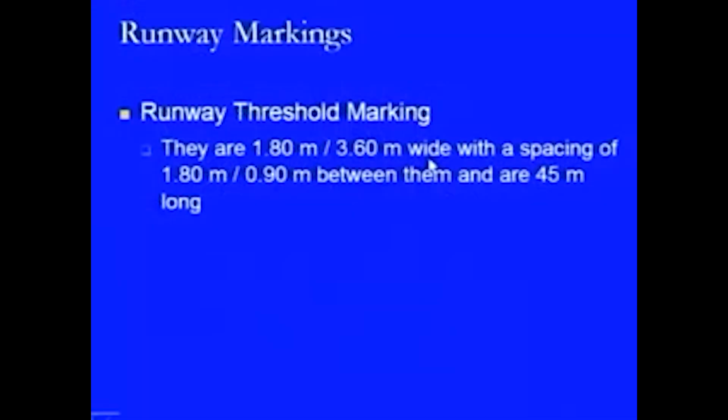These are generally 1.8 meters or 3.6 meters wide, with a spacing of 1.8 meters or 0.90 meters between them, and are 45 meters in length. So, these are the specifications for providing these markings.